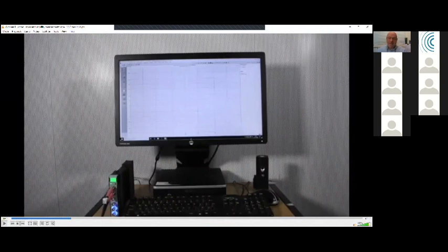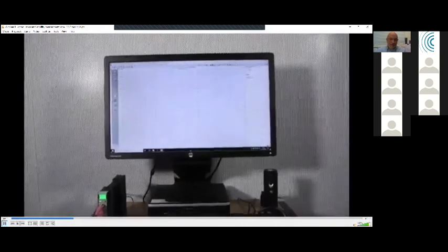Now we have a vibration calibrator here, so we can actually put the accelerometer onto this vibration calibrator, and it produces a known acceleration, very similar to calibrating a sound level meter with a known sound pressure level. So that allows us to calibrate the accelerometer. However, no such calibrator exists for the force transducer. And while we would hope that when we put the correct sensitivities into our conditioning amplifier we get the right answer, there is a way that we can check that the system is working as we would want it to.